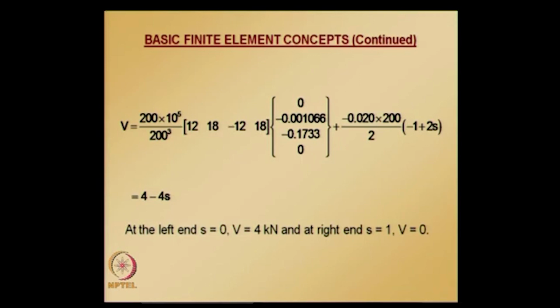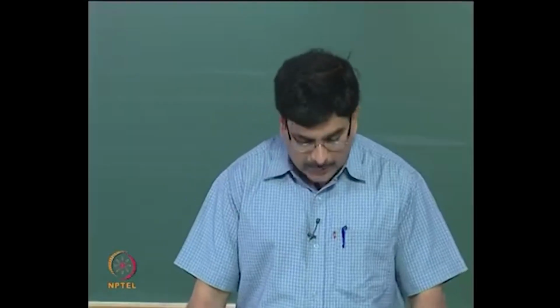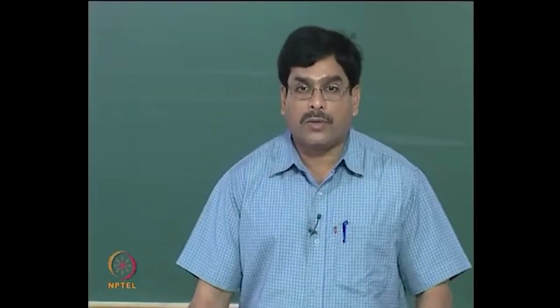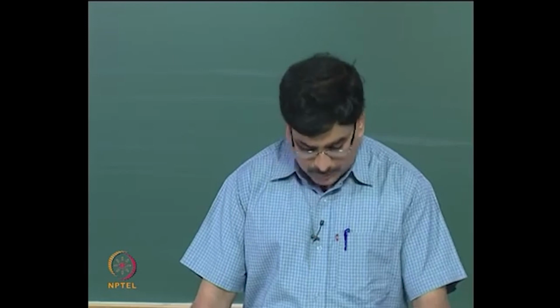So, now we have the element 1 solution and the element 2 solution. At any point inside element 1 or element 2, if somebody is interested in finding the moment and shear, we can substitute the corresponding S value and get the moment and shear at any point in either of these two elements. So, with this information we can plot bending moment and shear force diagrams.